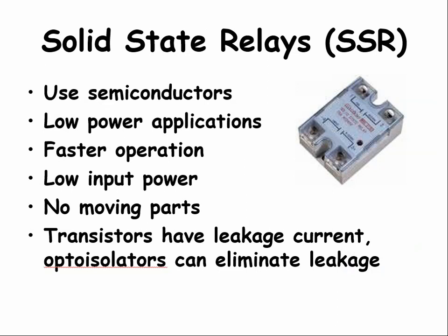This slide shows a solid-state relay. They are very common. Internally, solid-state relays use semiconductors to turn power on and off on the load side of the relay. We will not get into the internal workings of solid-state relays. Compared to the electromechanical relays, solid-state relays are used for low-power applications.